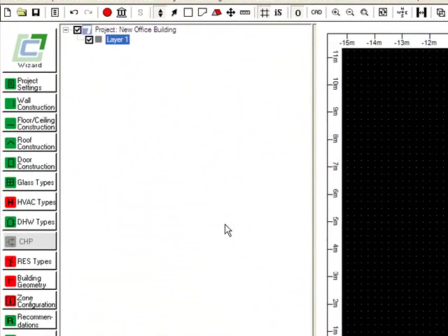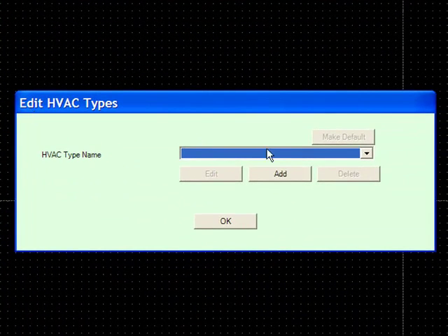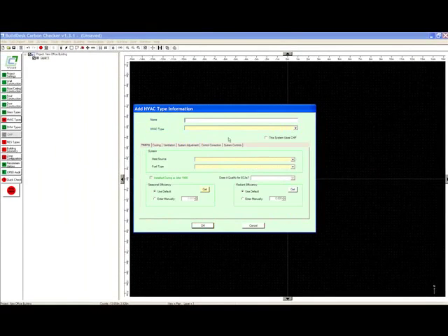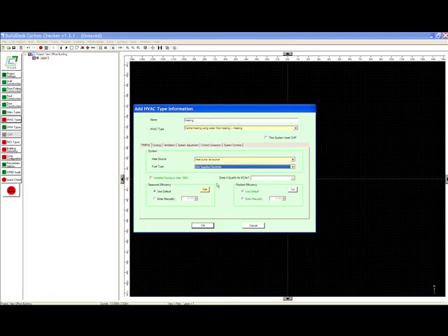And moving on, we now come to the HVAC, or heating system if you like. Again, we need to add a type. We'll simply call this heating. It's a modern building. We're going to make it underfloor heating. And for the various different types you use, we're going to have an air source heat pump. And we're going to power this by electricity from the grid.